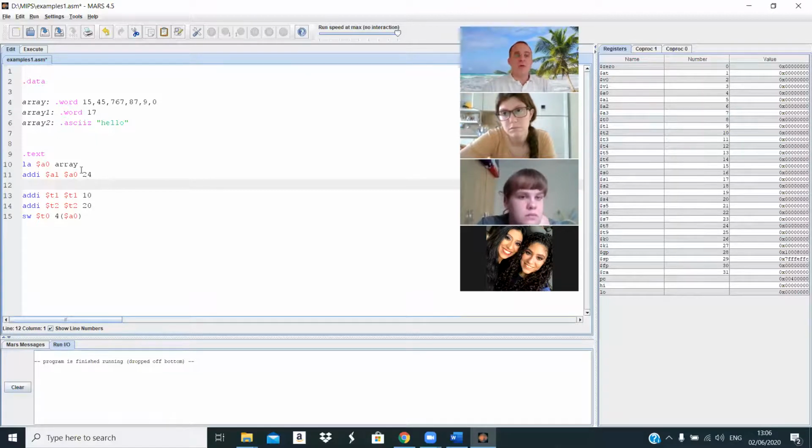And since I've already set up an ending point, which is a pointer to the end of the array, once I reach that, I can compare pointers. When the 2 pointers are equal, I've reached the end. That I could do. I don't think I did that in any example, but you could do that. The other way is to have an independent counter that counts up to 6, adding 1 every time, and when I get to 6, I'm done. And then your pointer to your actual array is incremented by 4 because it's a word. Right. Okay. Thank you.